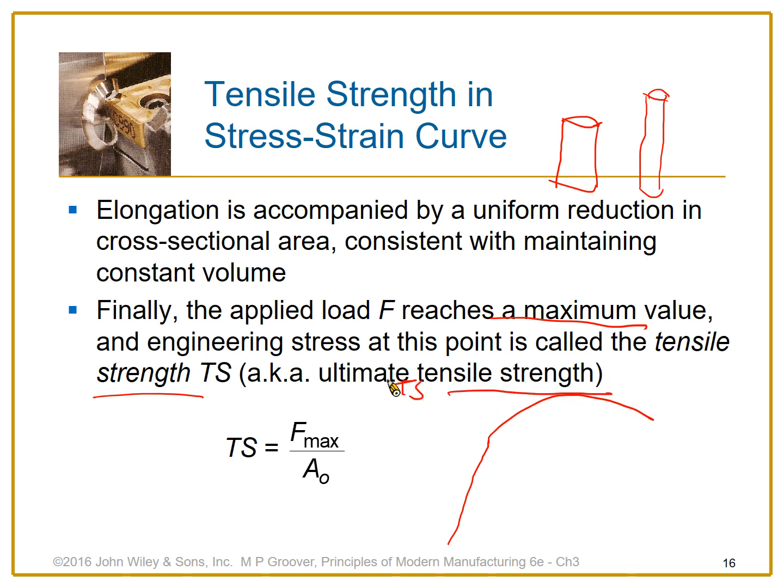It's the TS, the tensile strength, also known as the ultimate tensile strength. And that's how to measure it: the maximum force divided by the area A0. Okay, we will talk about this a bit later, because people might argue that, well, at this moment the diameter and the area have already changed. Yeah, but anyway, in this definition for the engineering version, you still use A0. So if you're asking for the engineering stress, then you still consider A0. Okay.